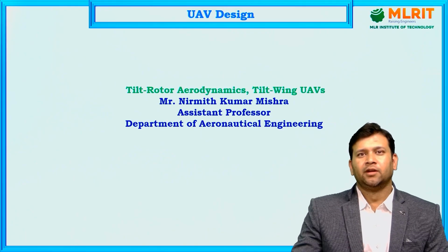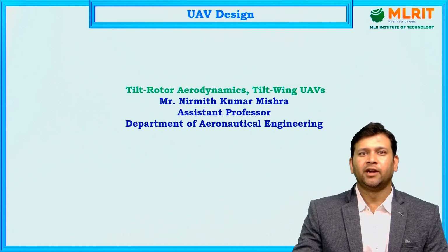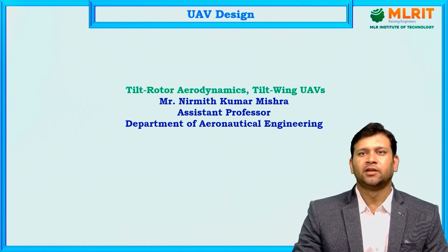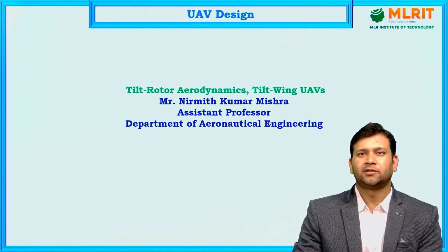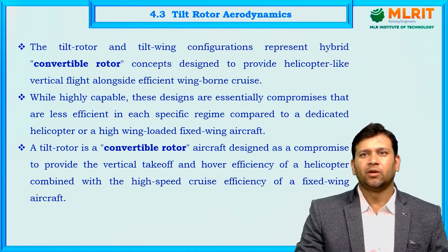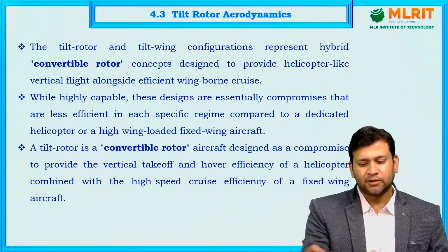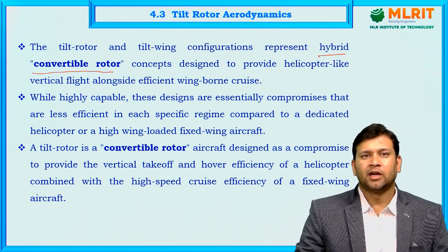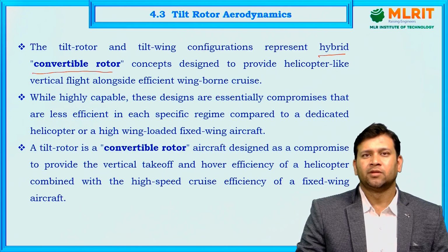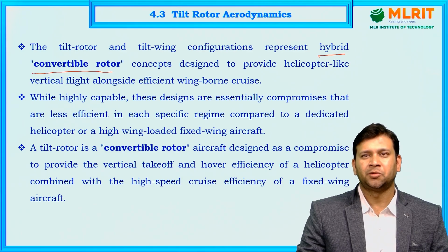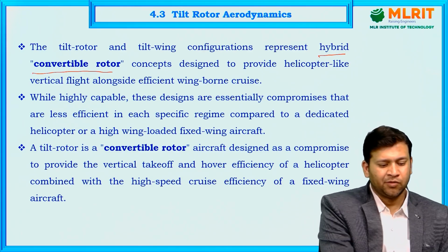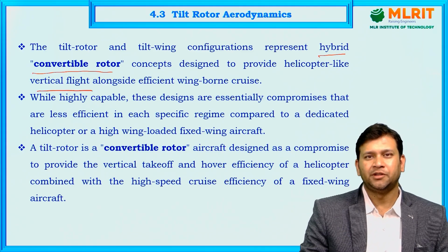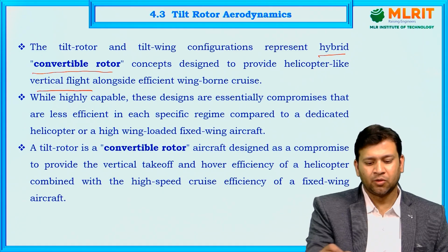Hello everyone, welcome to the course Unmanned Aerial Vehicle Design, and in today's lecture we're going to see about tilt rotor aerodynamics and tilt wing unmanned aerial vehicles. The tilt rotor and tilt wing configurations represent a hybrid convertible rotor, which is a concept designed to provide helicopter-like vertical flight alongside efficient wing-borne cruise.